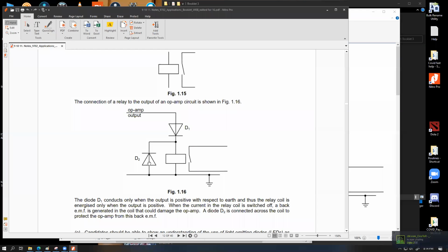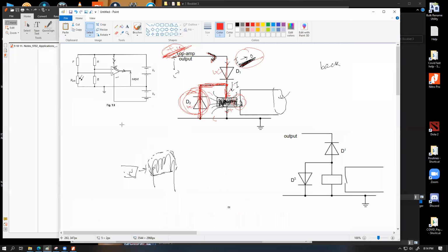Okay, I understand this part, sir, but how about D1? Doesn't it stop any current from the back EMF? No, because the back EMF essentially pulls the current in the original direction that the current was flowing. Let me show you in this part. In this case, this was the high voltage output, and this is the ground, the zero voltage, which means the basic current of this circuit was flowing downwards. So the back EMF will also try to maintain that current flow. So it will pull this current downwards. Now, if this pathway doesn't exist, it will pull this current through this main pathway. So D1 will not oppose that current flow because D1 is there to stop current flow upwards. It will very much allow the downward current flow.